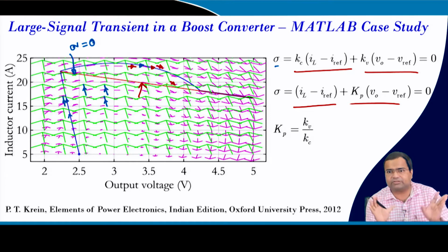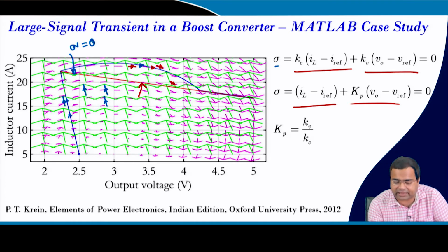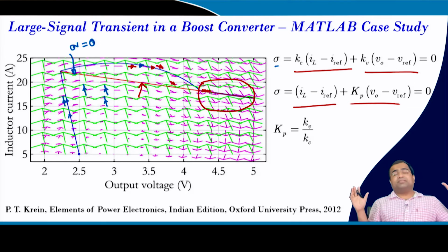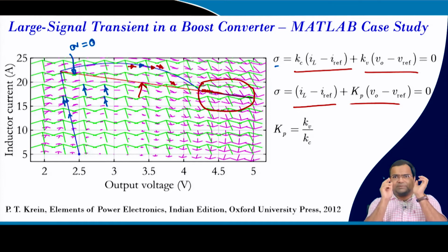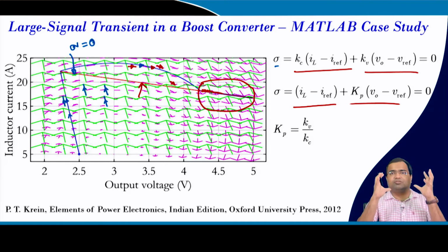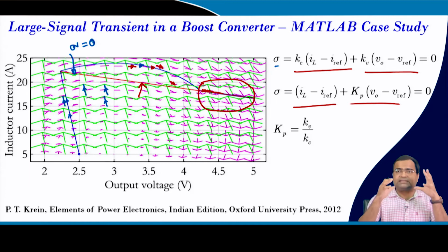That means this is very consistent, and once it comes to this region, it has a normal on-off operation with a very high switching frequency. That means the ripple is almost not visible, but it is actually going on. This concept is similar to the sliding mode control that we learned in lecture number 45.